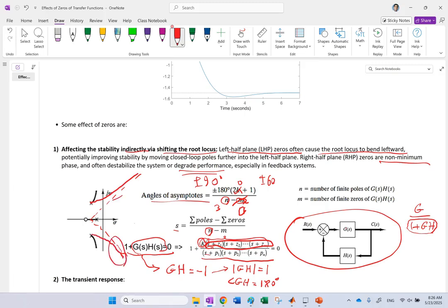And there we go, now you make them end up on the right hand side, and so now the poles will be on the right hand side, so the system becomes less stable by getting rid of that zero. By adding that zero, you make these angles bigger, so these branches stay more on the left half plane instead of ending up in the right half plane. So you see it affects the angles, and also the location of these intersects.